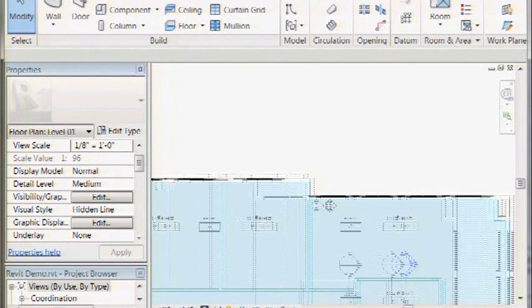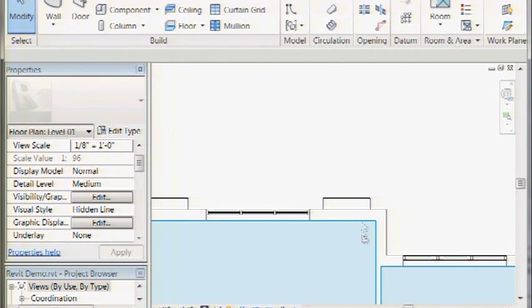The next thing I'm going to show you here, which is very common, is walls layered next to each other, because people want to show things like a wall core having different layers. Some firms make it their practice to have people build the gypsum layer and then the insulation and all of it on actual separate walls, and that will cause a huge issue.